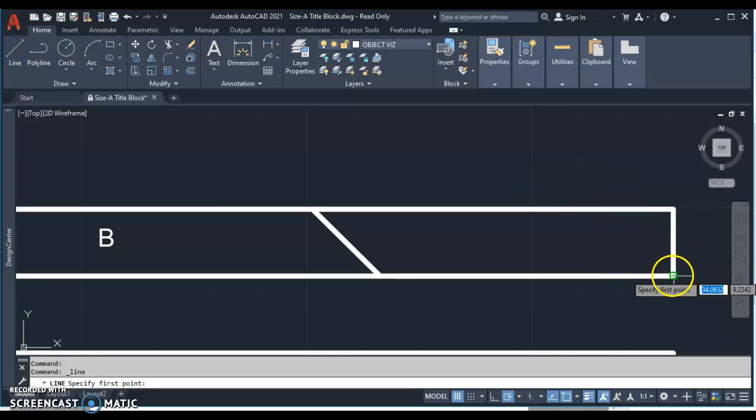From this end, I'm going to take the line tool, mouse over the endpoint, don't click, simply extend, get your extension command. Now part G is 2 1/4, so 2.25, okay, and it mouses up to right here. And I'll come in there.